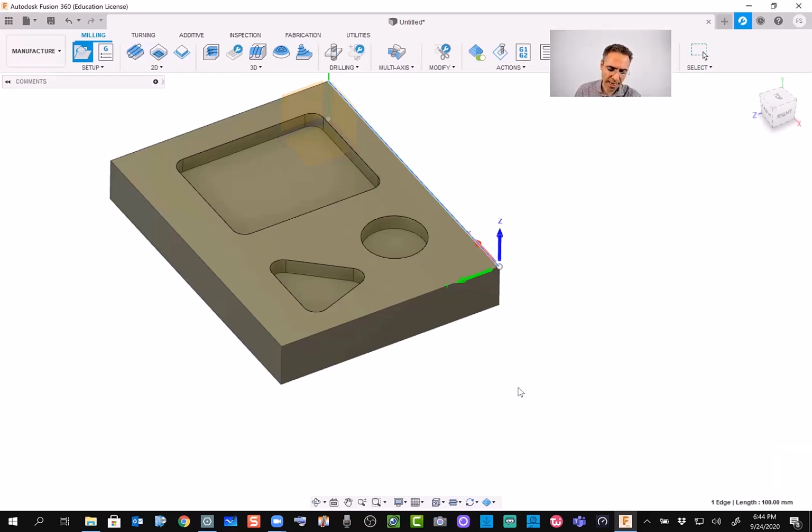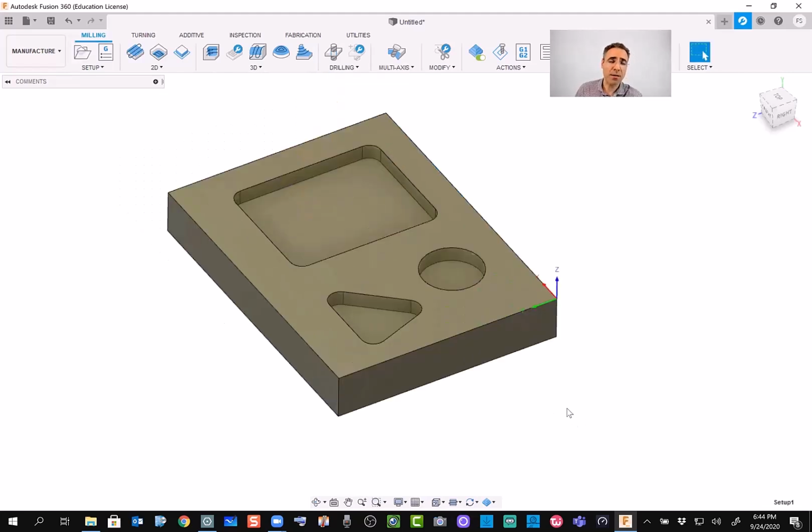All right, so I just click OK. So this is what I have here. I did my setup. By setup, two things that I did: I don't have any extra material to be removed, and I set my coordinates. I pick a corner because a corner is the best place. Later, when I place these things on the machine, I move my tool and bring it to this point, and I click on the home key and say, this is the 0 point for the tool. Okay. What is the next step?